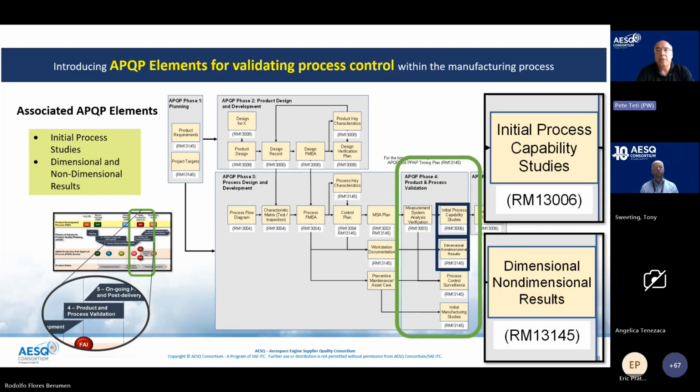However, when we look at initial capability studies above, those are generally key characteristics coming from a drawing, led by a design to build team and out of the PFMEA, where it's logical to implement process control techniques like SPC and apply capability studies for those types of features to reduce the risk of the process, not just the product and how things fit together.